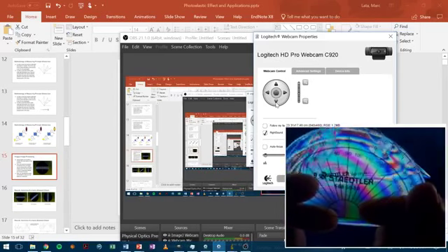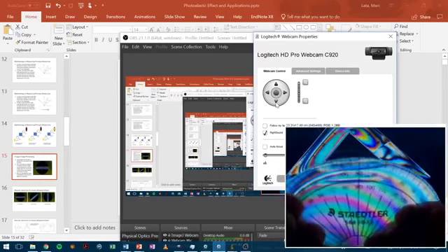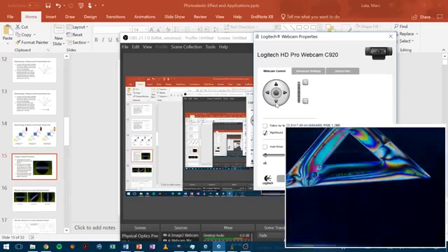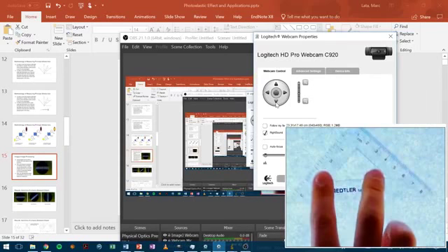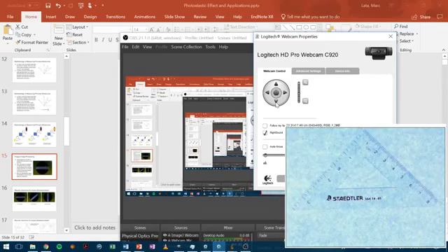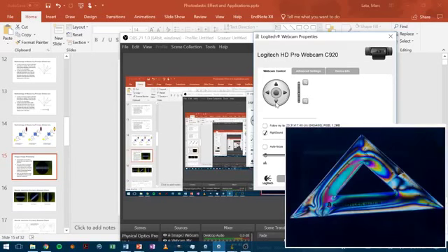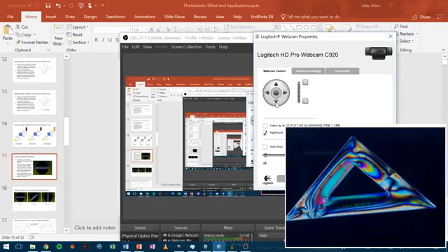Stress increases until a threshold at a point, then crack growth starts from this point. That part has a fracture on it. Oh no, that's interesting. If I remove the polarizer here, you can see there's no real sign that it's even in there. But then you put this in and you can see very clearly this weird manufacturing defect or something, because of polarization. These are called a crossed polarizer and analyzer set.